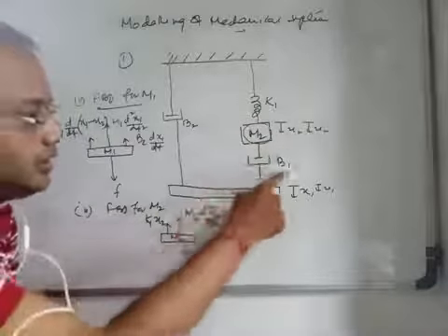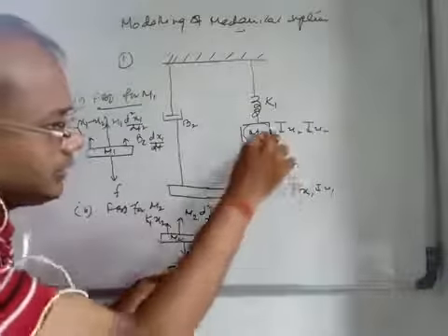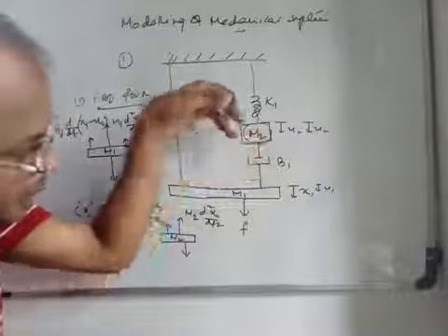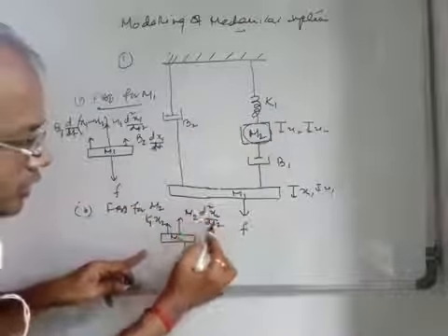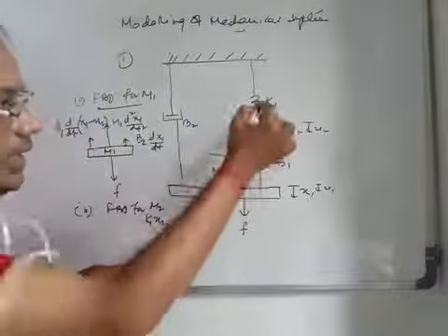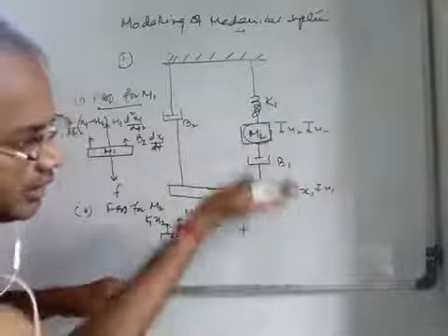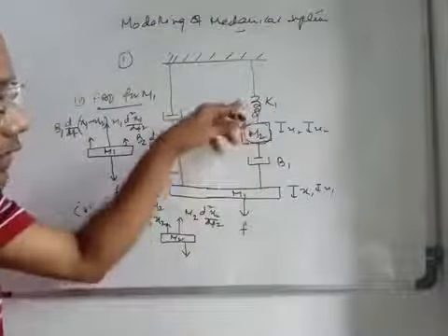So this is the b1 body which is connected to m2 in this direction. So you see if this m2 is connected and m2 is displaced by x2, definitely the inertial force m2 d2x2/dt2 is there, and as the spring is connected here and the body tries to move downward, definitely an opposition force k1 into x2 will come into play.